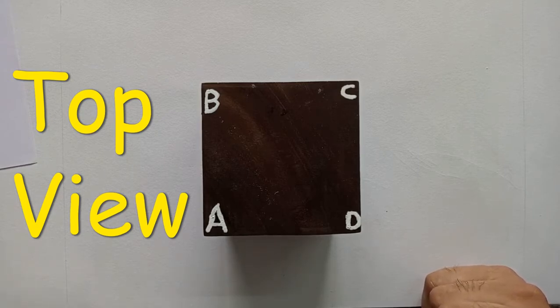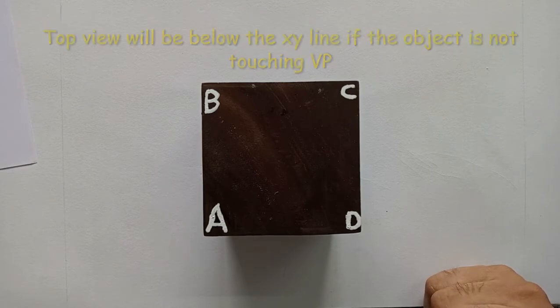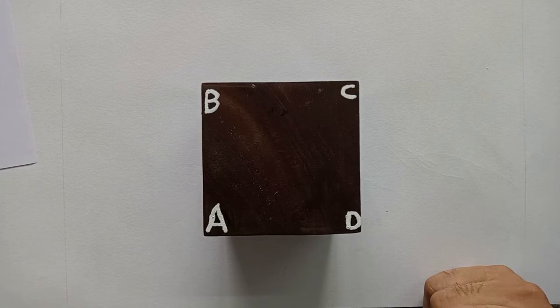As I have mentioned earlier, presently I have focused the camera from the top side and you are viewing the top. The view in the top, that is the top view, is represented on the horizontal plane. So we are considering the object in the first quadrant. Whatever object is present in the first quadrant, its top view will be below the xy line. So below the xy line, you will be getting a square with 50 mm edge length.